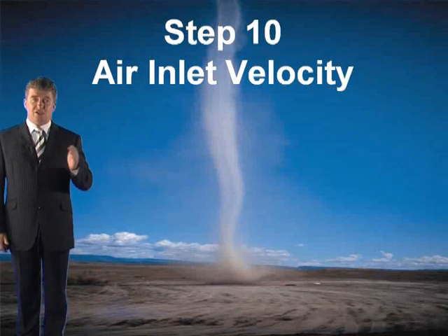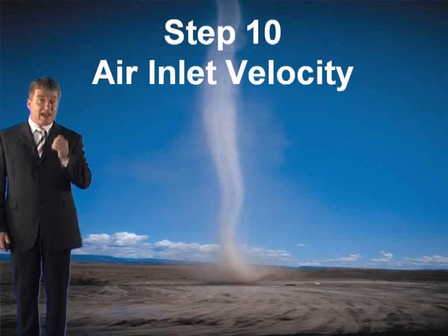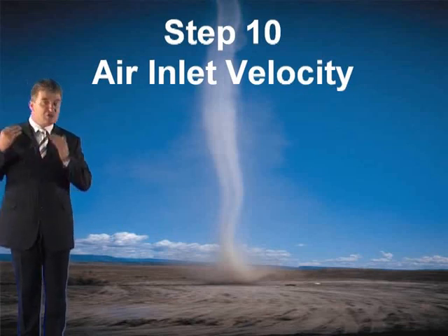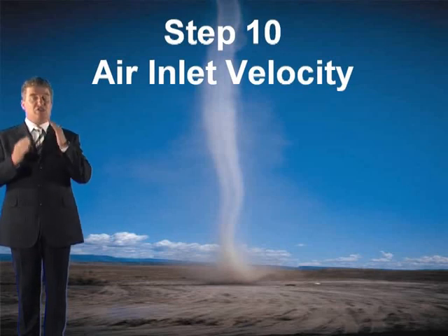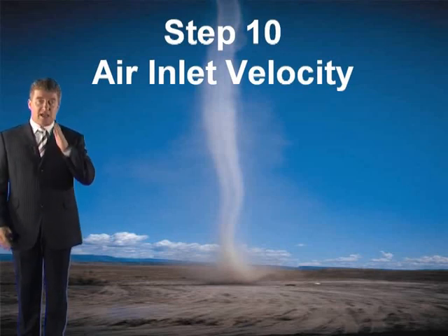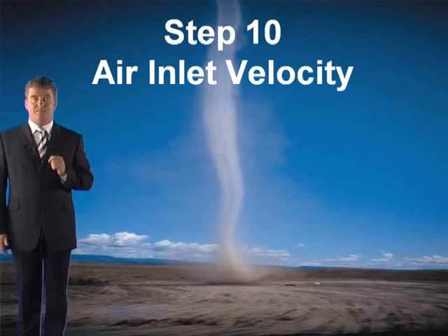Now, step 10 is to check the air inlet velocity, if necessary. Again, this is a natural ventilation system, so this does not kick in, and all the air is going to come in from the reservoir anyway. So this does not apply in this particular case. It's natural ventilation, so again, you can skip step 10.